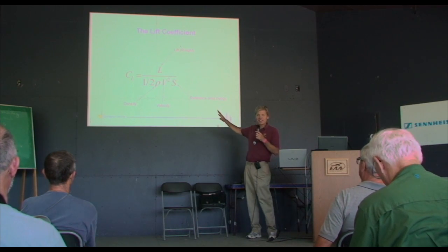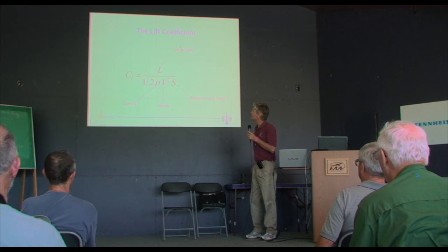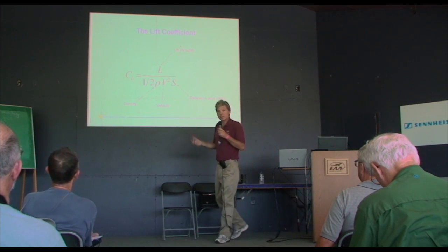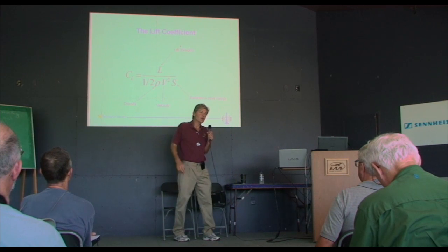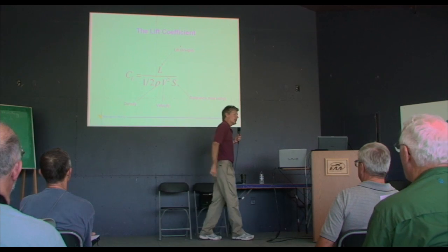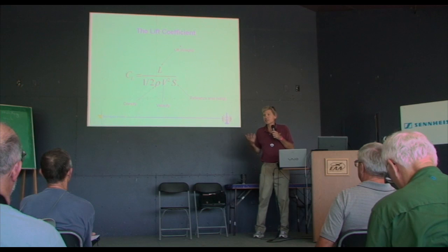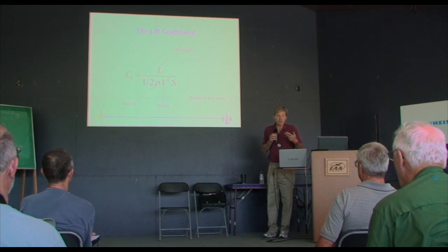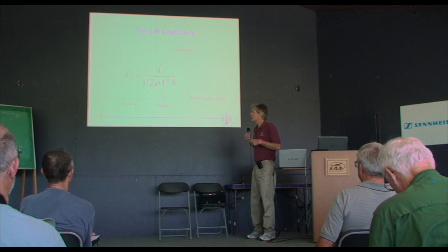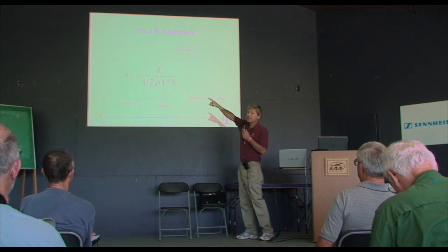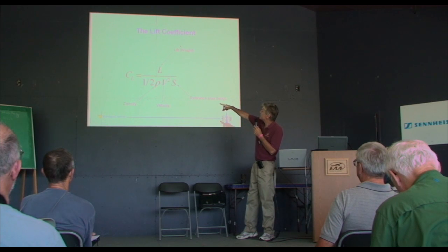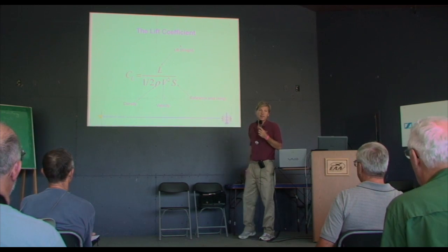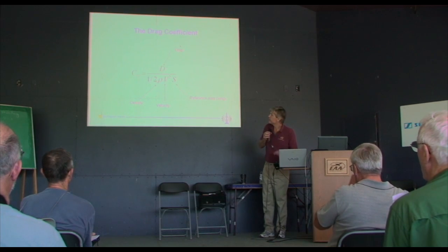Again, a lot of you have seen this, I apologize for going back to square one, but you basically have the lift coefficient. The lift coefficient is a non-dimensional form of the lift of the wing. Why do we use the lift coefficient? Because it can be used to describe the lift characteristics of a wing, and it's not dependent on the particular velocity or the size of the wing. It is equal to the lift divided by 1/2 times the density times the velocity squared times the reference area of the wing. So that's our lift coefficient.